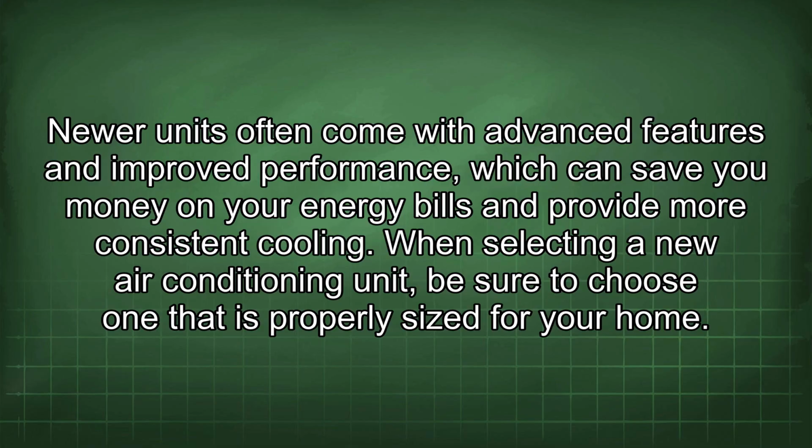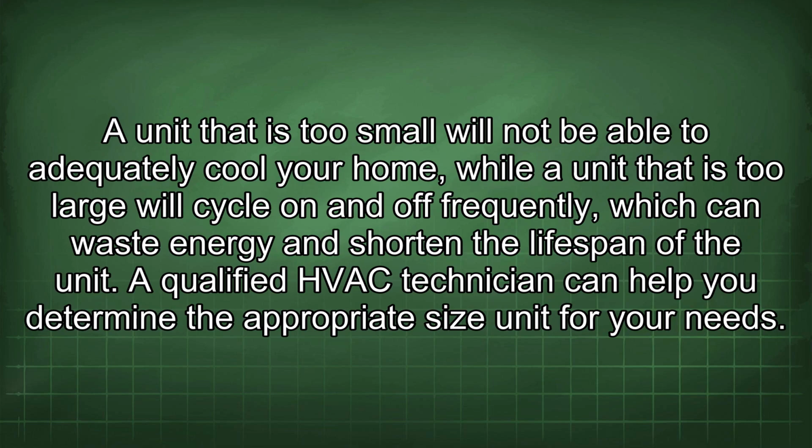provide more consistent cooling. When selecting a new air conditioning unit, be sure to choose one that is properly sized for your home. A unit that is too small will not be able to adequately cool your home, while a unit that is too large will cycle on and off frequently, which can waste energy and shorten the lifespan of the unit. A qualified HVAC technician can help you determine the appropriate size unit for your needs.